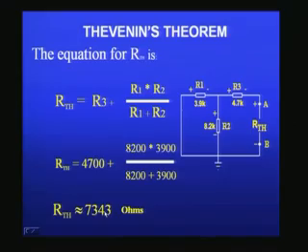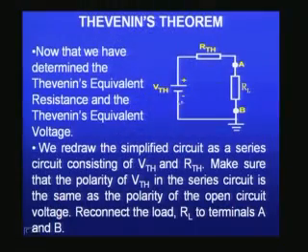So, we have calculated V Thevenin, we have also calculated R Thevenin, and once we do that, we can simplify the original circuit by just having V Thevenin here, as you can see, and you have an R Thevenin, which you have now calculated for this example, and just you have to connect the RL, which is the ultimate load resistance we want to apply.